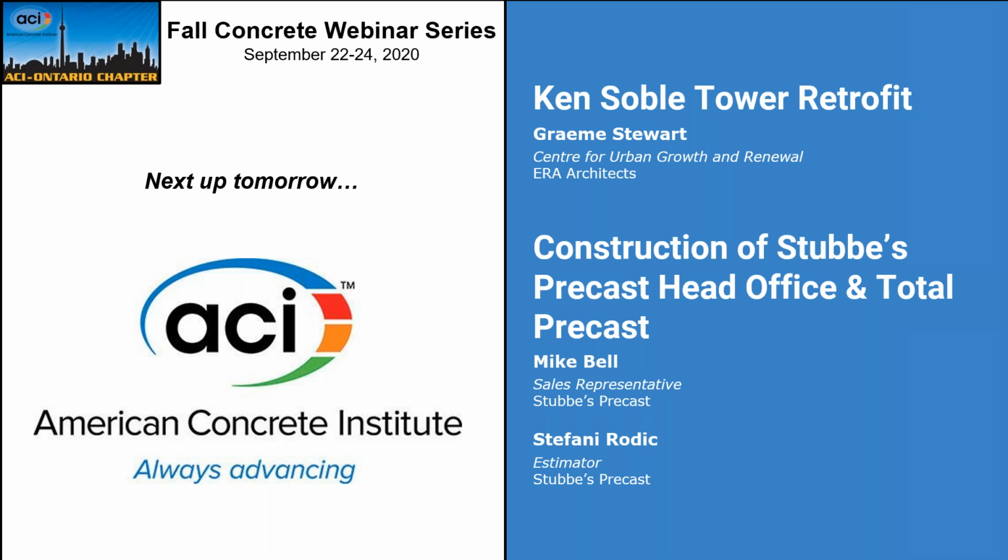Well, as you well know, Stacia, we were involved in this a lot at Atrio. It was to be able to compensate for the setting of the floors, so that we got flat floors. It wasn't for sway. And the consistency that was looked for in order to predict for the presets, you have to know in advance. So in the chart of variability that I showed on my slides, we were within plus or minus 8% of the design value on a consistent basis as we measured, over somewhere in the order of 1.5 years of production. But it did involve an awful lot of quality control measures at the start.